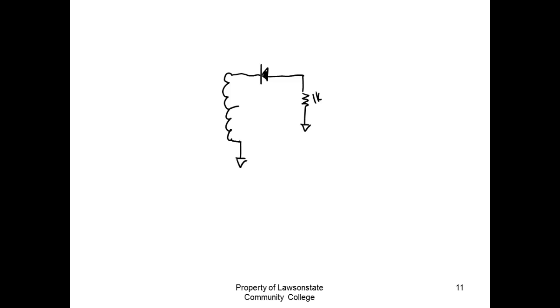And of course we could look at it and this is rated at 12.6 volts, but we understand that it's not going to be exactly 12.6, it's going to be something around that, right? Because that 12.6 is rated at 110 volts on the primary at 1 amp. So if we don't pull 1 amp, we're going to get a little more than 12.6 volts. It all depends on that, but they're going to give you the rating on the transformer. Does that make sense? Okay.